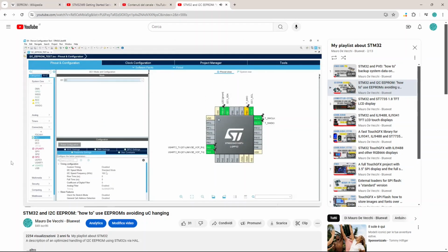Anyway, the question is, as any STM32 has a flash on chip, can we use it for saving data? Can we emulate an EEPROM on flash? Indeed, usually program and constant data don't use the whole flash memory availability. Usually, in a project, we can have part of a microcontroller flash memory unused, even a large part of it. So can we use the free area on flash, saving our data instead of using an EEPROM added to the project? The answer is yes, that can be done.